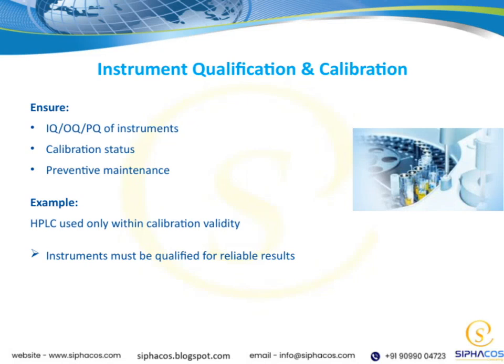Let's talk about instrument qualification and calibration. It's essential to ensure that our instruments undergo IQ, OQ, and PQ processes. These steps confirm that the equipment is installed correctly, operates as intended, and performs reliably over time.